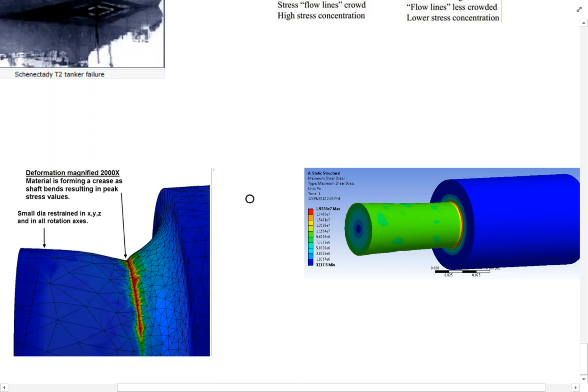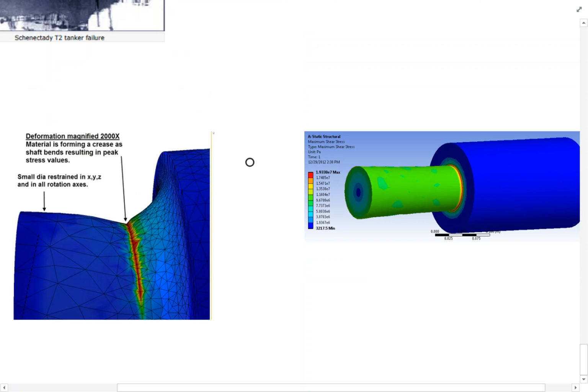And this is just a couple images here, again, of an FEA where you've got a sharp corner here, and this is exactly what you'll see when we do this analysis. Right, you're looking at stress in this case. So you've got obviously the blue being the lowest because it's the largest cross-sectional section through the part. The green, again, smaller cross-section, but the area to really worry about again is that sharp corner, which you see here. And you can see the impact of the meshing.